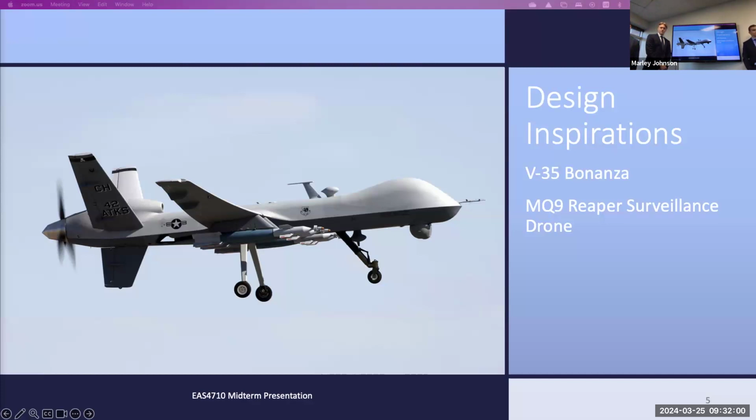Find a CG. Yeah, you can do that. We're trying to do rough Excel calculations more than a CAD. We don't have a full assembly with the battery, ESC, motor, all that stuff in a CAD. But we have Excel with the distance from the nose and the CG, so you have a spot where you believe your CG is. We know where our CG should be, obviously with slight changes in printing and all the weight differences, and the fact that we don't necessarily know exactly how much our wings are gonna weigh until we lay them up and weigh them. It's still a rough calculation. Also, we're working on the CAD to get every component and see the CG.